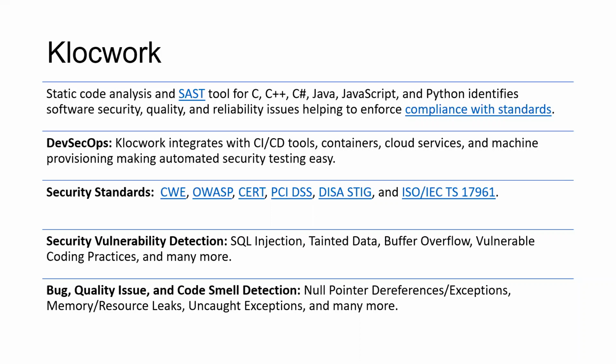So Clockwork has a set of rules on its own, plus we support verifying industry standards. Plus, you can write your own custom checks in Clockwork as well. So if your internal coding guideline says global variables should start with Z, or a class name's second letter should be a capital letter or something like that, you can write that as a configuration or a checker in Clockwork and you can deploy it.